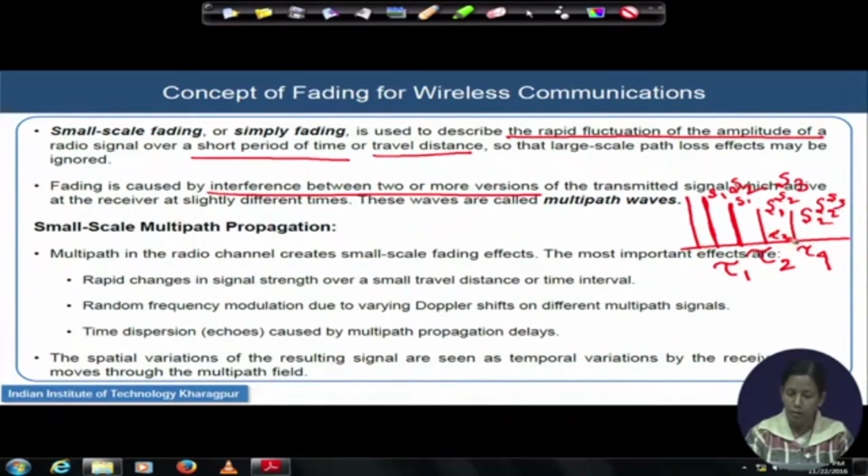So, you see at each and every timing instant, delay instant I should say, there is a very complicated signal model you are going to receive. The addition of the multiple signals with their corresponding changes in the amplitudes and phase, its additive effect, you are expected to receive in the receiver front end. So, this combined phenomenon, or the changes of the original signal because of the other signals that are superimposing on it at the receiver front end, is termed as fading.